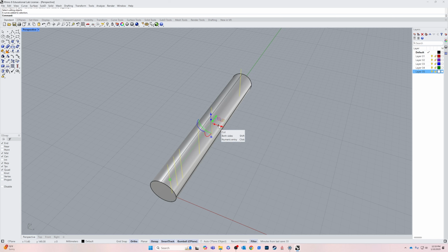I hold down shift and I click on it and then I drag it. It creates these cutting lines. And then I just kind of release and it now cuts these segments. All right. And then so I can actually go ahead and select these lines now and delete them. They were just there for my cutting benefit.